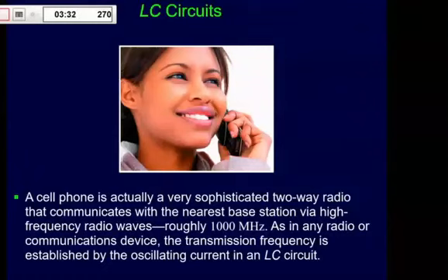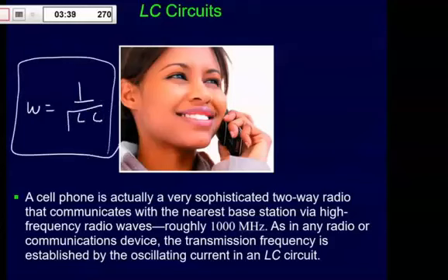So these circuits really are such that they want to accept this special kind of frequency. And so if you're building something like a cell phone that you want to only accept certain kinds of frequencies and basically block all the other noise out, one way to do it is to have an LC circuit, because again, it's a really finely tuned circuit that only allows, or at least strongly prefers, oscillations right around that angular frequency there. Questions on that?